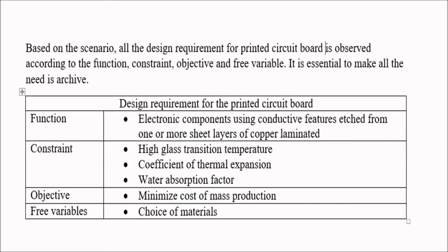A high glass transition temperature is very important for the printed circuit board to guard against barrel cracking and pad fracture during soldering operation. And for the coefficient of thermal expansion, this assembly process exposes the printed wiring assembly to more temperature shocks than the typical through-hole process. At the same time, the increase in lead density causes the designer to use more and more layers, making the board more susceptible to problems concerned with the base material's TCE.